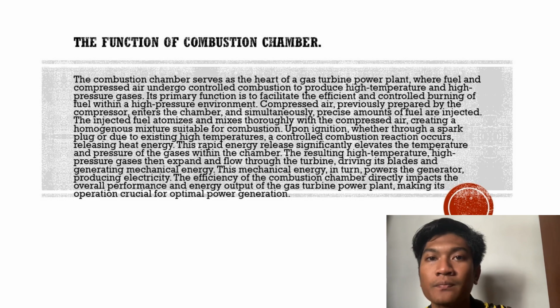simultaneously, precise amounts of fuel are injected. The injected fuel is atomized and mixed thoroughly with the compressed air, creating a homogeneous mixture suitable for combustion. Upon ignition, whether through a spark plug or due to existing high temperature, controlled combustion reaction occurs, releasing heat energy. This rapid energy release significantly elevates the temperature and pressure of the gas within the chamber.